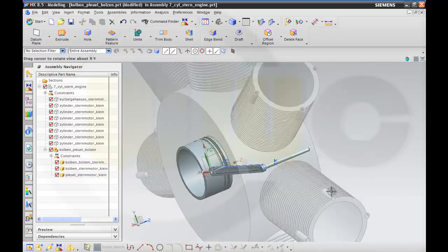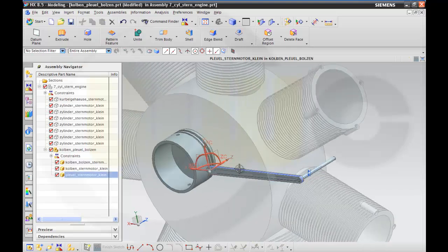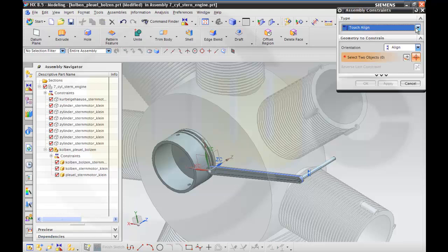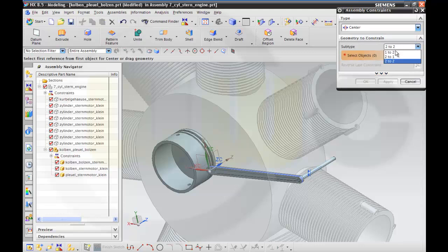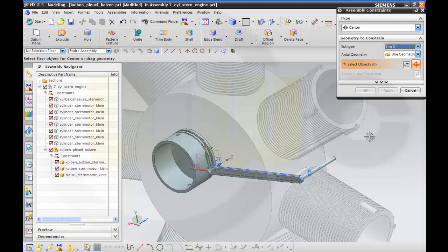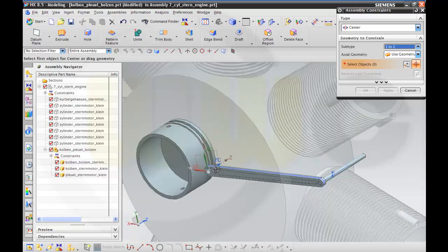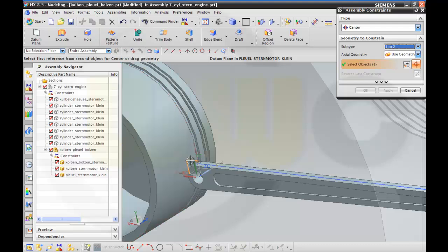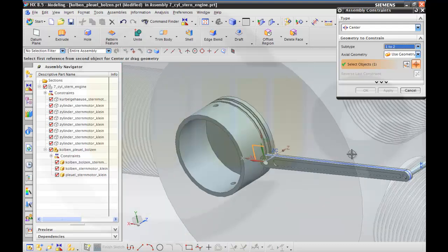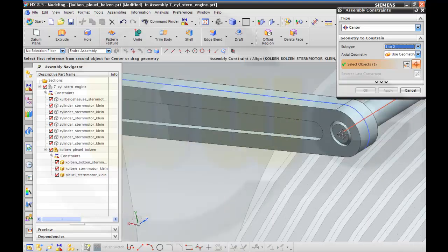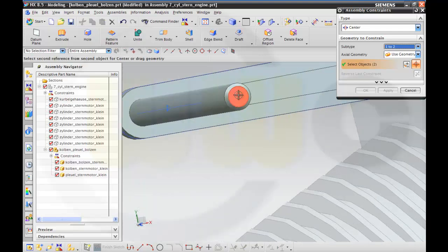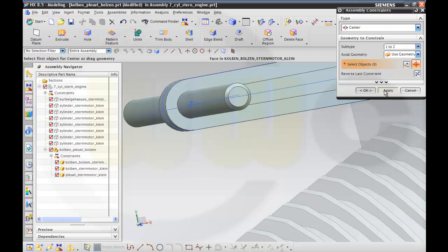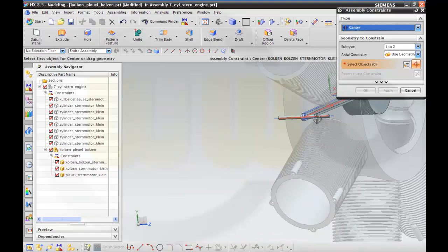And then I want to align that plane between these 2 faces. So I go for constraint, use center. Yeah. And it's 1 to 2. First one should be this plane, and the 2 other objects should be this face, and on the other side this face. And apply. Looks good.